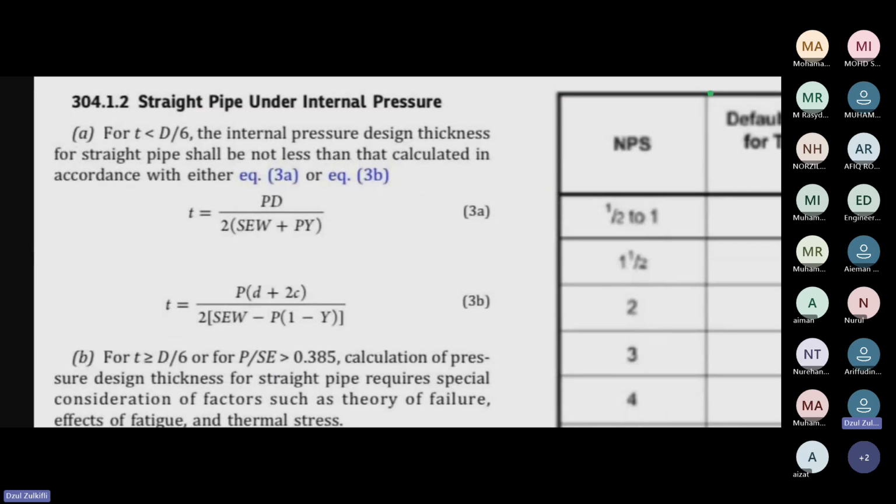What FFS does about the stiffener ring is that FFS will calculate whether the stiffener ring that you have is going to be a limitation for FFS or not. To put it very simply, if you have a stiffener ring that's too big, then you cannot do Part 4 and Part 5.